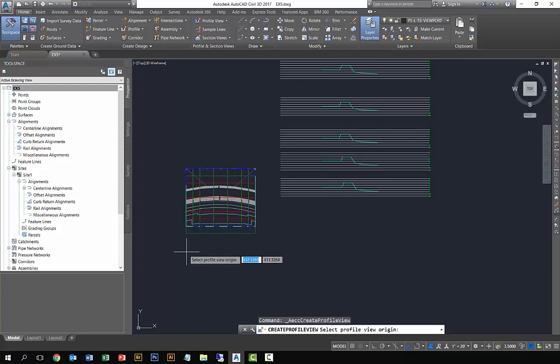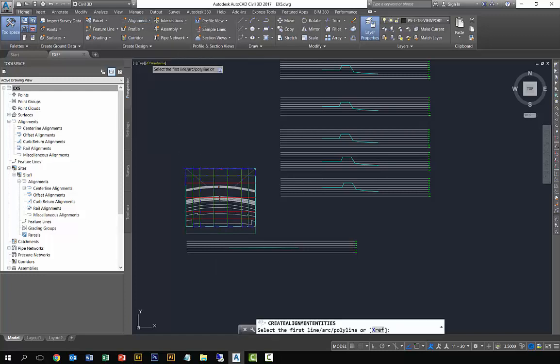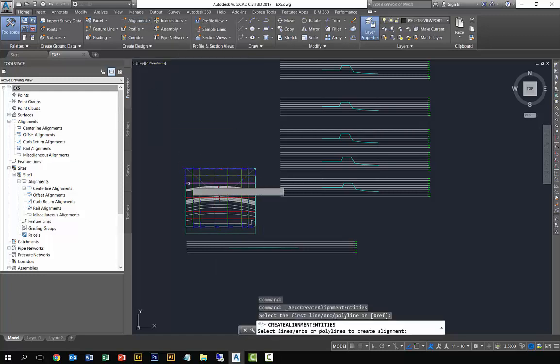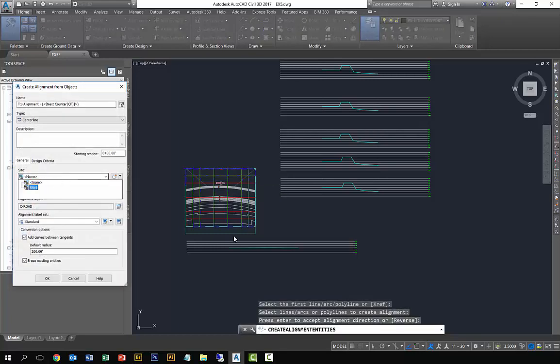You're going to accept the defaults. There you go. Now, here's something you need to pay attention to. Is the baseline the same between the cross and the longitudinal section? So, in making this model, I anticipated that the lowest level that should appear on the model should be -20, so that there would be enough material to create the waffle.